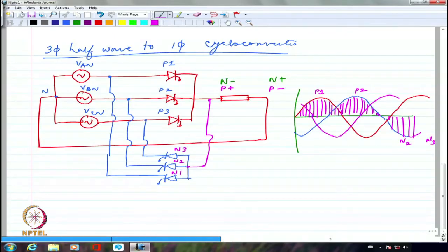So I will have again reduction in the frequency, but I have taken as though alpha equal to 0 or even less than that. So I am starting right from the transient condition. Otherwise alpha should be calculated somewhat like this. That's what we said. So we are looking at the whole thing as though we have to fire the P converter such that ultimately the current will come down to 0.